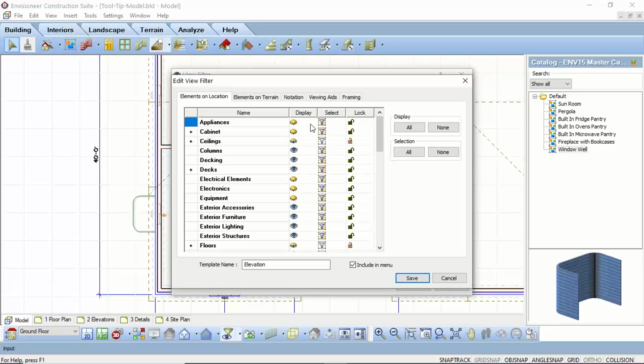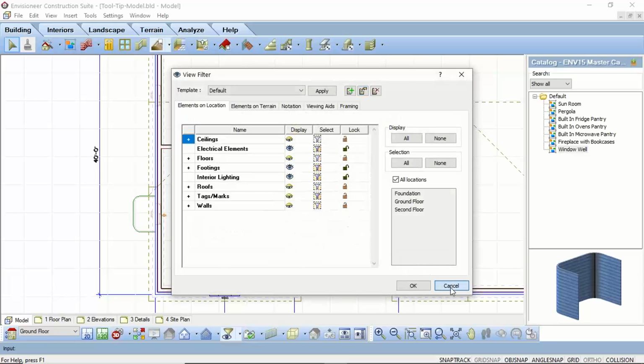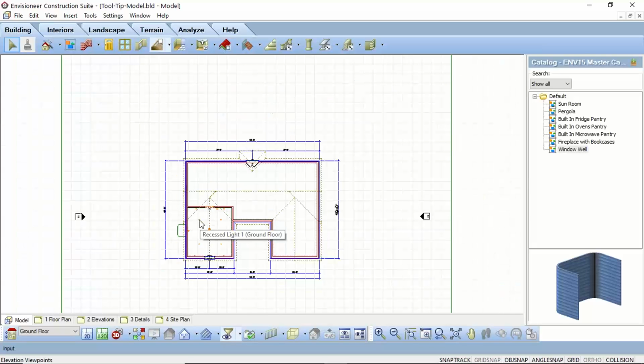So the only thing that's going to be analyzed in the model when it's being created as a working drawing is going to be the elements that need to be seen. Your walls, windows, doors, roofs, ceilings, floors, your decking material. Again, all of those things that you would want to show on the exterior of your plans. So that's one time-saving tip that I always point out, just because elevations without that view filter option turned on will take a lot longer to insert than if they did not have those elements in them.